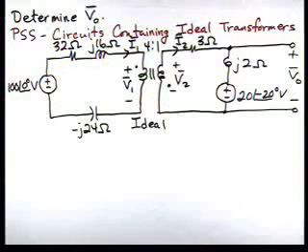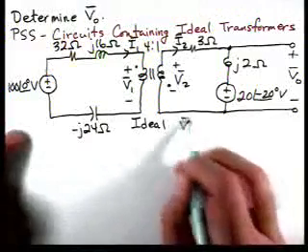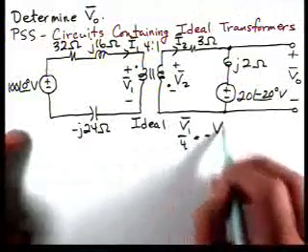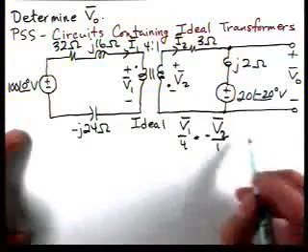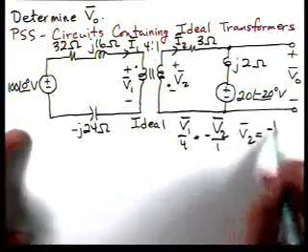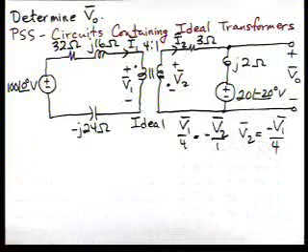And if we look, one of the first things it says is look at the circuit diagram, determine the assigned voltage polarities and current directions in relation to the dots. For the voltages, one voltage is referenced positive at a dotted terminal and the other one is referenced positive at the undotted terminal. So that says that V1 over 4 is going to be minus V2 over 1, or V2 is equal to minus V1 over 4.